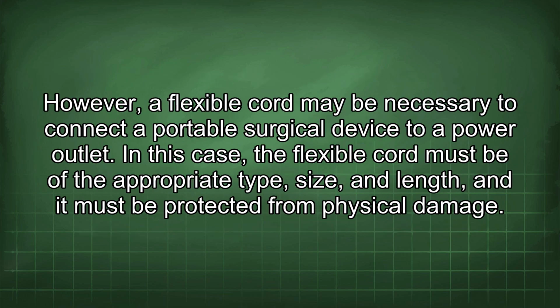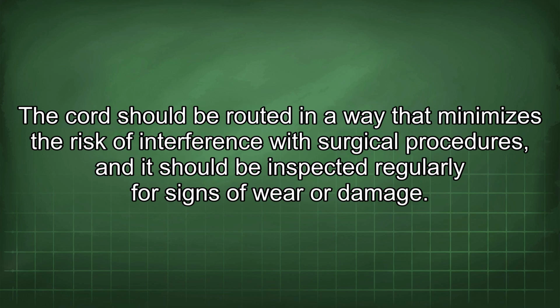However, a flexible cord may be necessary to connect a portable surgical device to a power outlet. In this case, the flexible cord must be of the appropriate type, size, and length, and it must be protected from physical damage. The cord should be routed in a way that minimizes the risk of interference with surgical procedures, and it should be inspected regularly for signs of wear or damage.